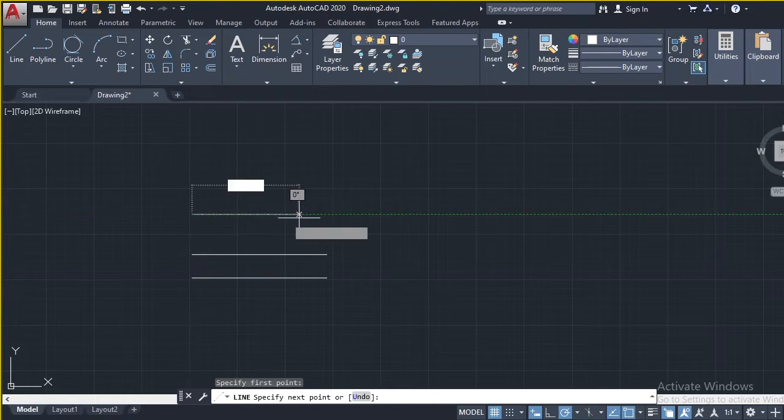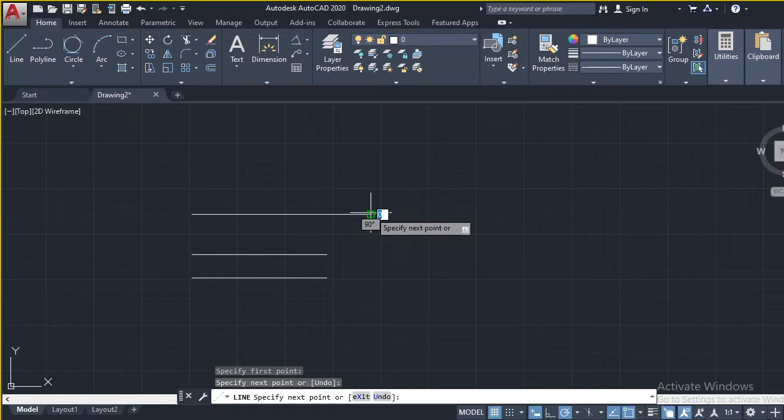Something like this. I want to make an arc that will touch these 3 lines. This is useful for civil engineers who want to design a parapet. It is an easier way for you to draw the arc.